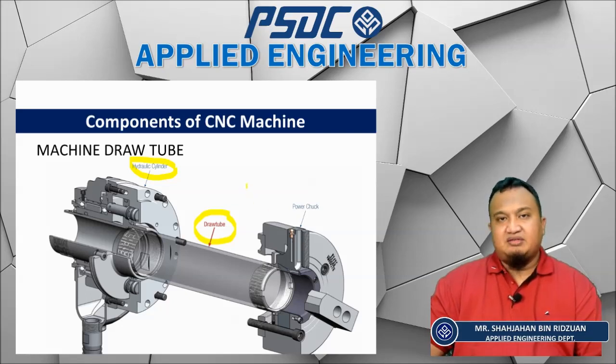So bear in mind that our 3-jaw chuck force uses hydraulics. Whatever you do, make sure your fingers are not in the 3-jaw chucks when it closes or opens.